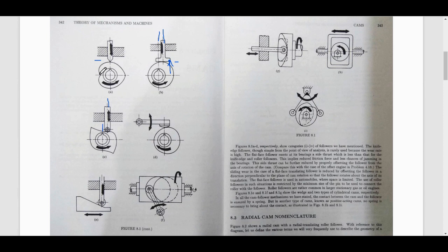This part is the cam. You can see there is a keyed shaft in here, so this will turn the cam like this, and the follower will go up or down. There will be some spring keeping this follower pushed in that direction and maintaining contact. That is usually not shown. So here is the other cam now.